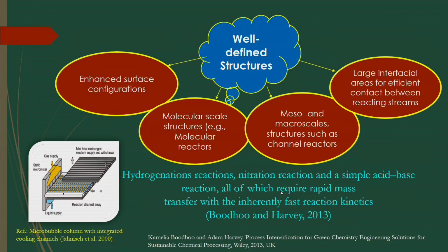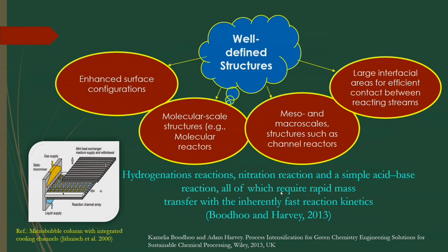Another important feature is called the well defined structures. You have to develop the reactor in such a way that you make some internal provision inside the reactor to obtain more interfacial area for efficient contact between the reacting system, like packed bed, trickle bed, even some other microstructured packing materials through which the fluid will be flowing, getting more contact between the fluids and more mass transfer. So, enhanced surface configurations can be done by this packing material, structured packing materials.